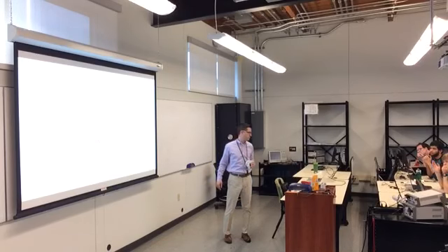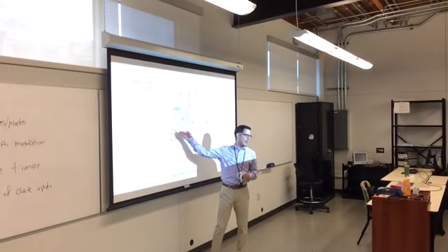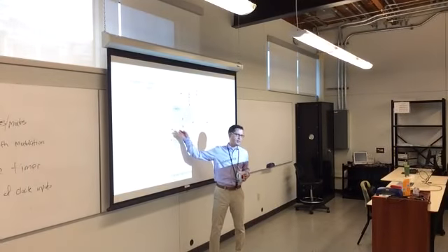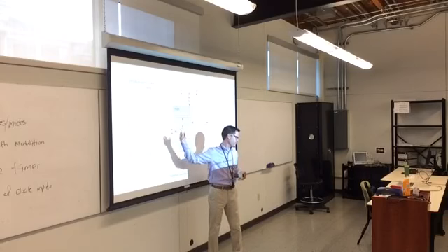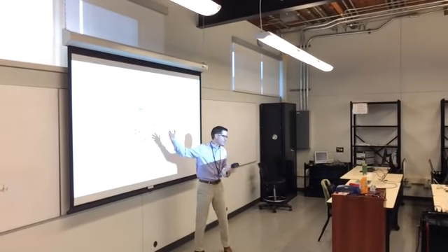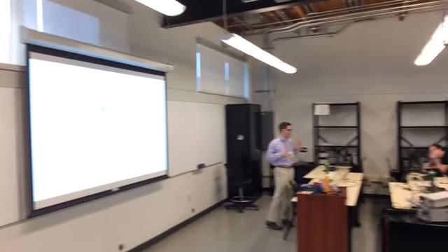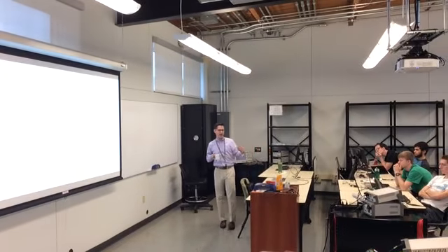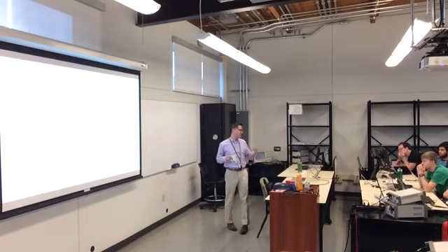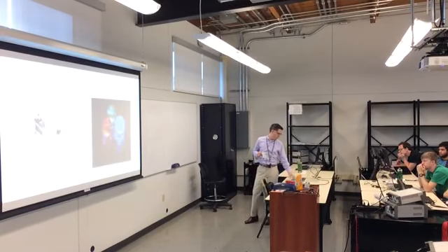Darren? Your clock speed. Right, so if this clock is going at 1 hertz, is there any way I'm going to generate a 10 kilohertz wave? Right? The number of bits that I have matters. It's how much I can time. If I've got a super fast clock, but I can only store like 2 bits, I'm not going to have the resolution I need to store all of my values.